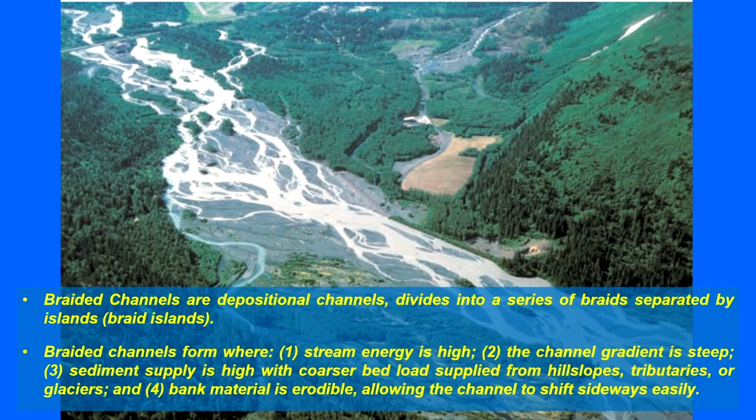So these are the main points: the energy is high, the gradient is steeper, and sediment supply is high, okay, with coarser bed load supplied from the hill slope and tributaries, and bank material is erodible, allowing the channel to shift sideways. So these are mainly not very deep channels, but you will see that they have a tendency to migrate. Okay. So this is another issue with braided channels.